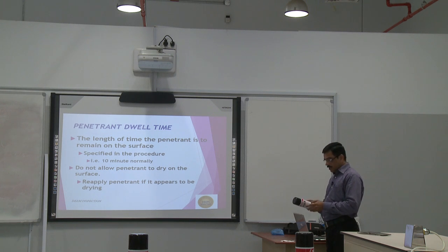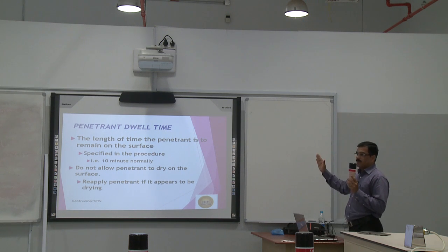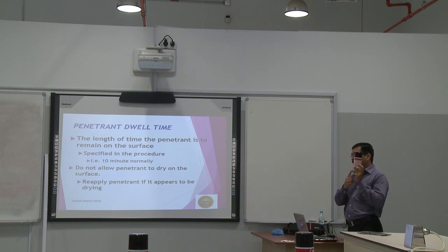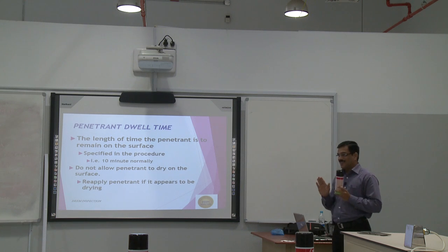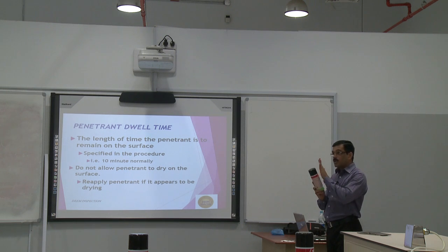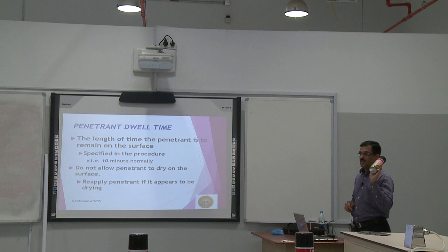If it is not mentioned, the manufacturer says it is 10 minutes dwell time. So we will follow either the manufacturer's recommendation or the procedure. If the procedure says 5 minutes, we should still follow the manufacturer, because the manufacturer who made the product says a minimum of 10 minutes is required. We cannot reduce that, so we will follow only the manufacturer's instructions.